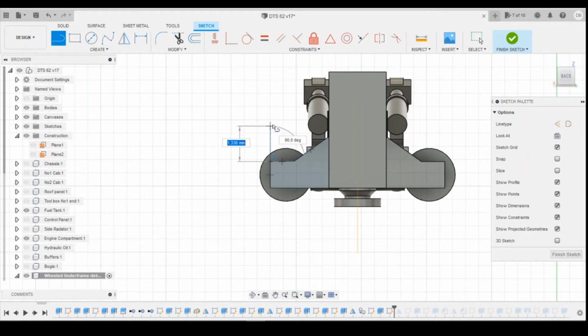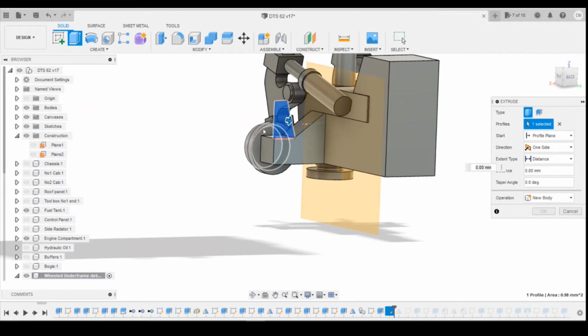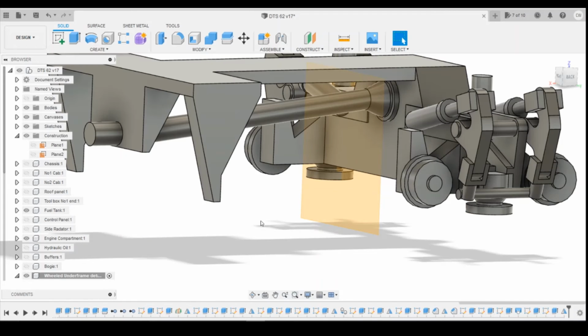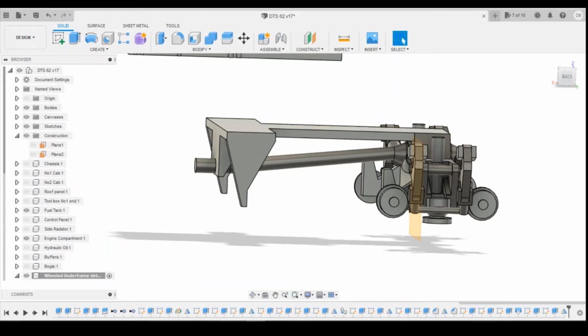So we're going to go from that point, we're going to come up 1.4 millimeters. I'm going to come across 0.5, and then I'm going to come diagonally down to that point there. So we're creating that shape. Again, we're looking for representing it, not necessarily perfection. And then we're going to extrude to the back of the wheel there, tell it to join, click on OK. Then when we jump forward in the history beyond all the mirroring, we've got it on both sides.